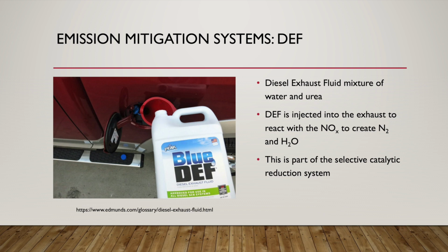So DEF is a combination of synthetic vehicle-grade urea and deionized water, and it's injected into the exhaust stream. What it does is it breaks down the harmful emissions of NOx and turns it into nitrogen and water. And this can reduce the emissions of NOx up to 90%. The primary purpose of diesel exhaust fluid is to facilitate compliance with federal emissions standards.